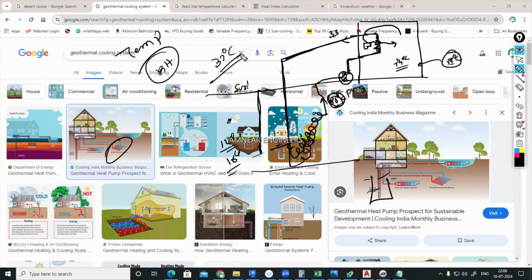Now, this sweat or the water molecules has to evaporate. So if the sweat water molecules have to evaporate, it needs latent heat of evaporation. So that latent heat of evaporation, the water molecules will be absorbing from the body. So the body will be losing the heat, the body temperature will decrease, the body cools. That's why our body is effectively using the latent heat of evaporation to decrease the body temperature, correct? But you can see, if the atmosphere is already having 100% relative humidity, what will